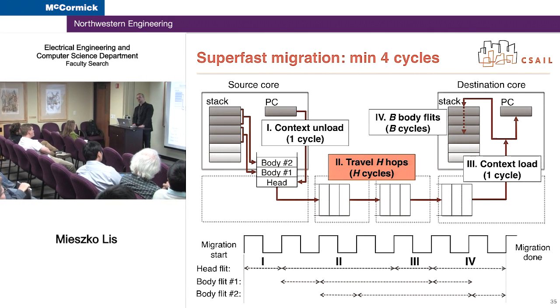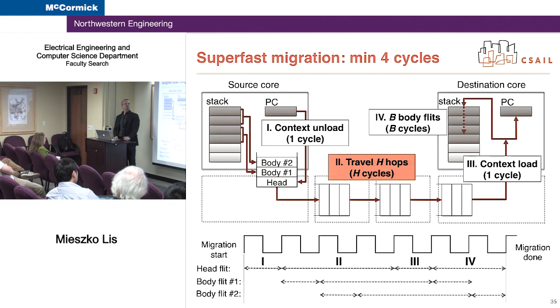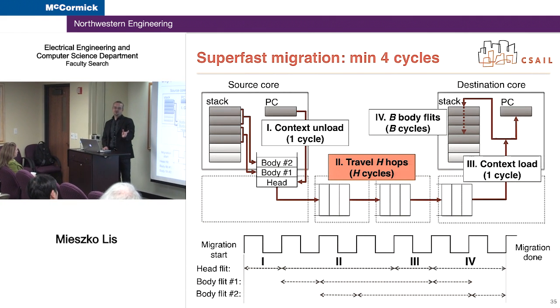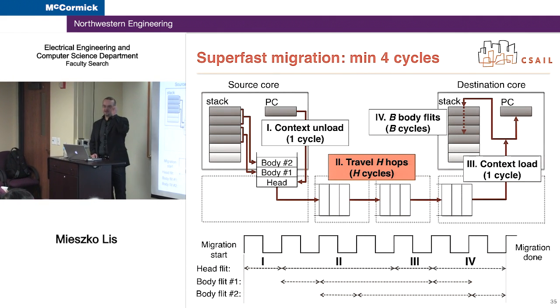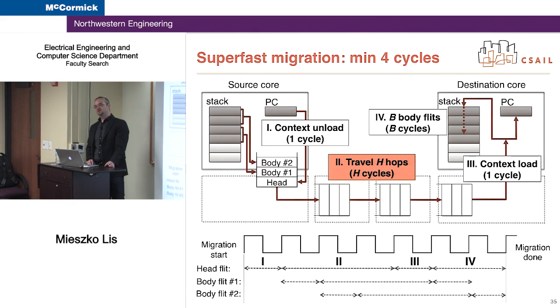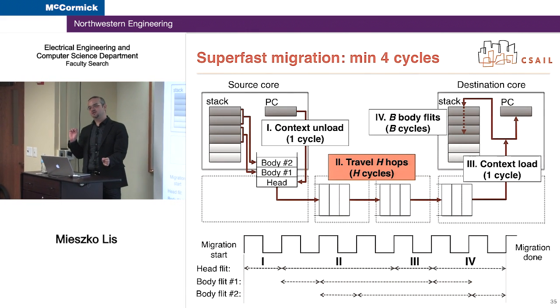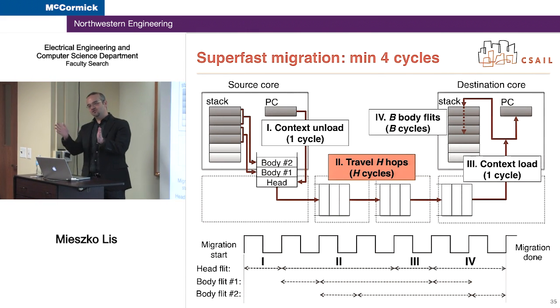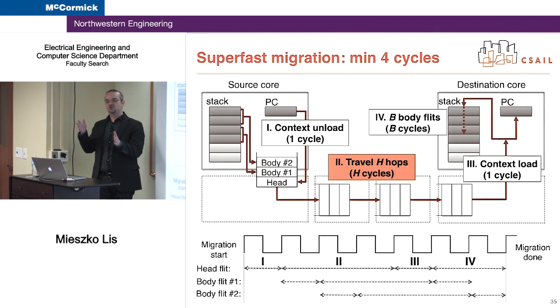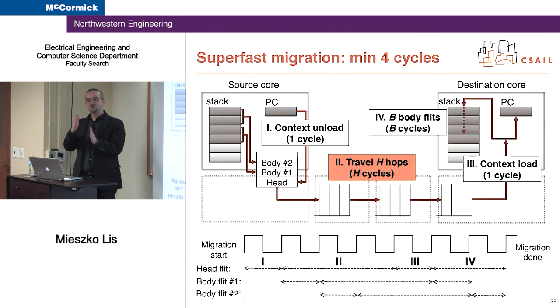If you don't bring your instruction cache with you, your instruction cache miss rate is higher by 7%. That is to say, from 0.001% you get 0.001007% misses in your system. So basically, it is not worth doing anything about it.